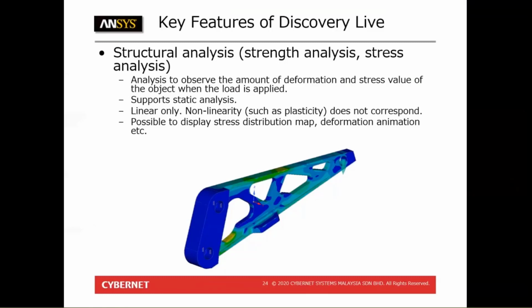So any type of non-linearity, such as material non-linearity like plasticity, is not supported in Discovery Live. For the structural analysis, the result will be displayed as a stress distribution map, deformation animation, and so on.